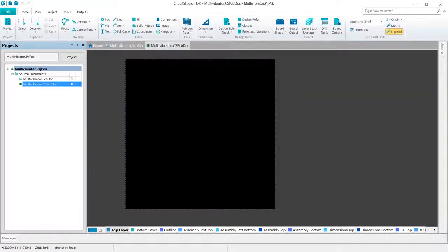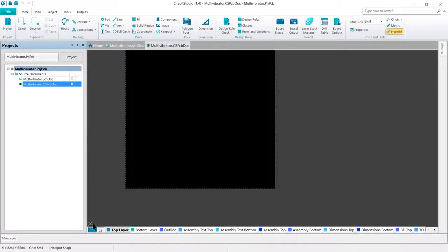This is a small PCB, so let's just make a 30mm by 30mm square for now. We will start by setting the origin and defining our snap grid. There are two origins used in the software, the absolute origin, which is the lower left of the workspace, and the user definable relative origin, which is used to determine the current workspace location.